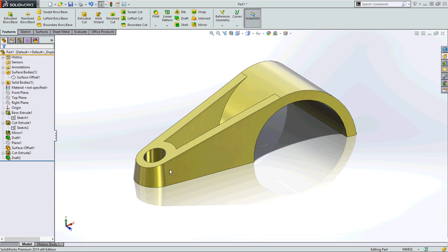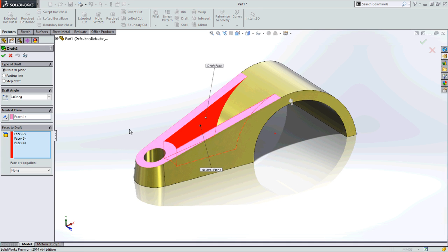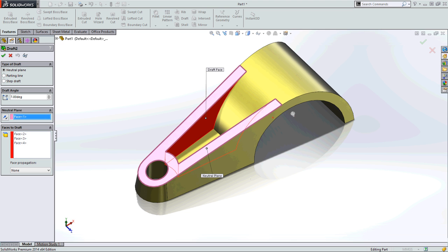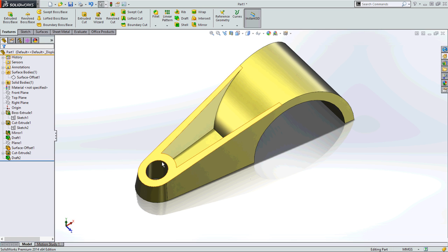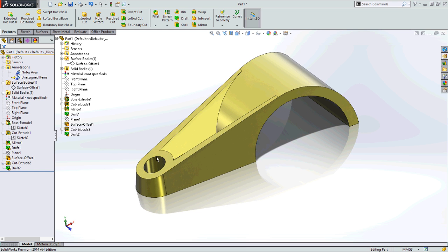That's not correct. If I change this and I say, well, maybe our neutral plane is this one down here. Check our direction. That looks good. Now I got this tapered thing here, and it started down there. It's not 7 millimeters between that point and that. It's 5 point whatever, and it's even less back there. So that's not quite right.